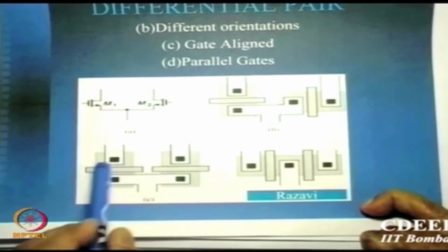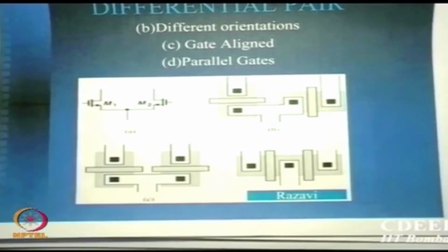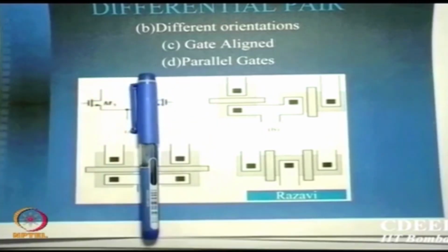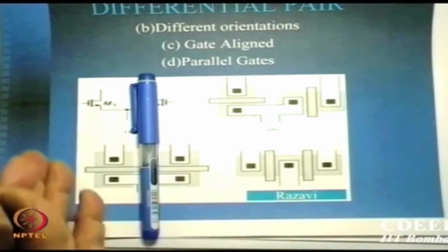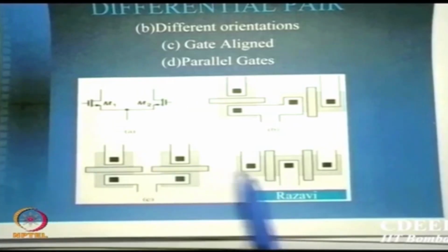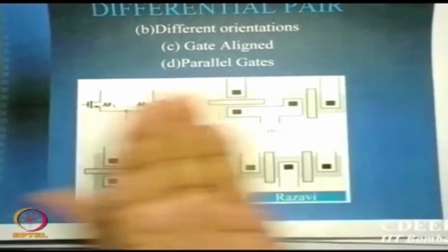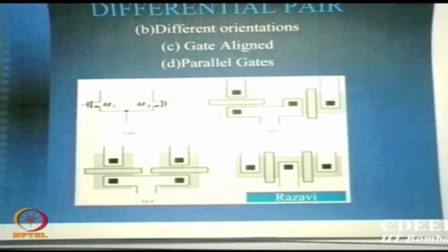Now you can see identical drains, identical source. So if you take symmetry across this, the diff amp has symmetry requirements, that is what we have been saying all the time. So if you lay it out like this, only then is the diff amp symmetry easily accessible to you. In this you can break into more devices if you wish, but fold it, this is called folded symmetry. Do like this and again it is symmetric. Symmetry is all that I am looking for in any lithography process, okay, and therefore any layout I make has much more worry about symmetry points.